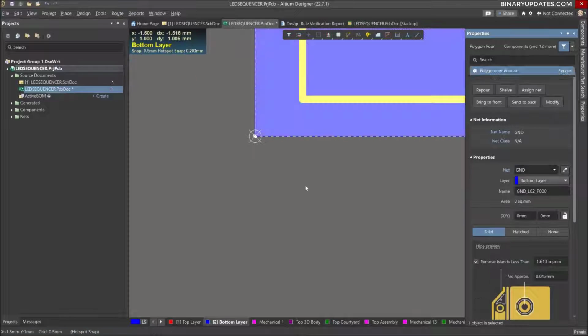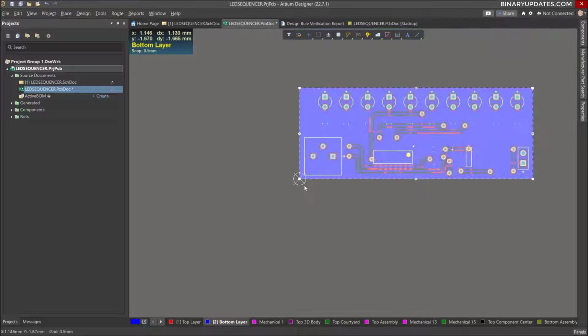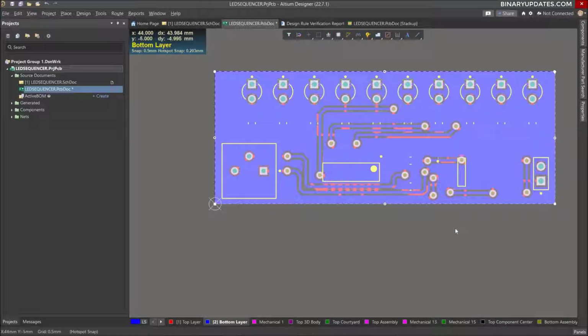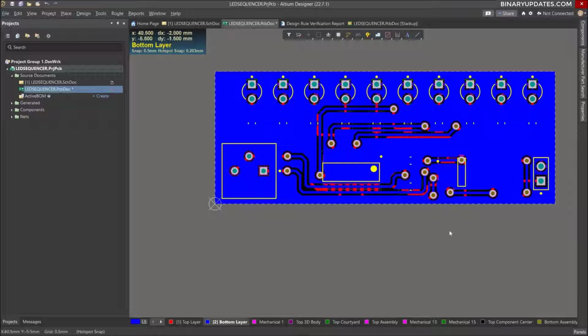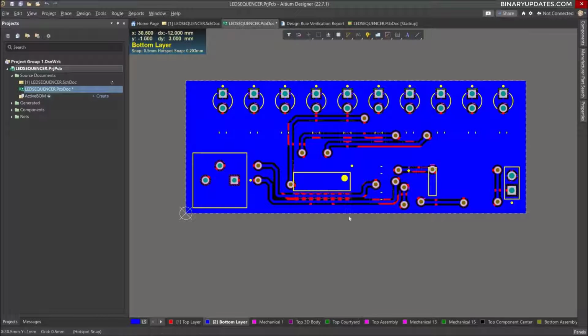Now right click to deselect, and now you see the PCB board file shows up here for us, right? So after adding the polygon pour, we can really generate the Gerber files, but I think it needs to be done in a more optimized way.